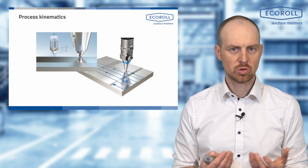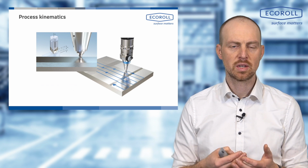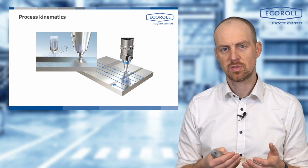Here, a pneumatic cushion is built up through the careful rotation of a spindle or a wobble plate, and when it eventually discharges, a striker is accelerated and forcefully hits the actual hammerhead, which is then firmly pressed into the surface.